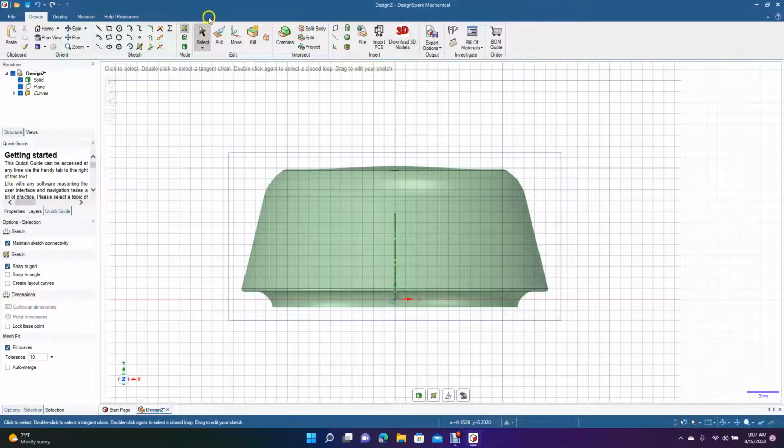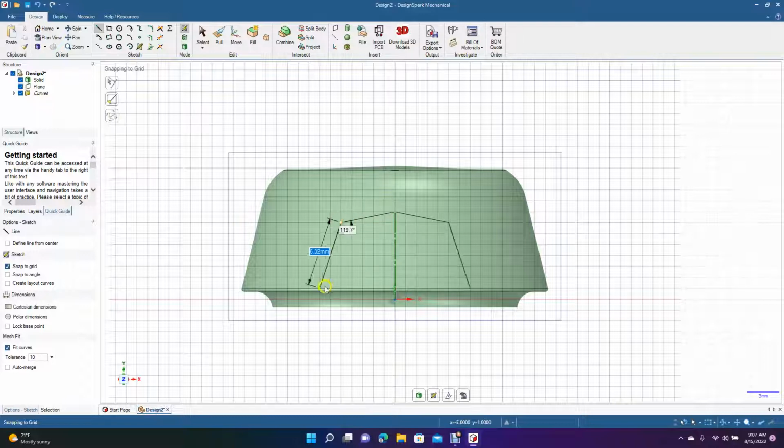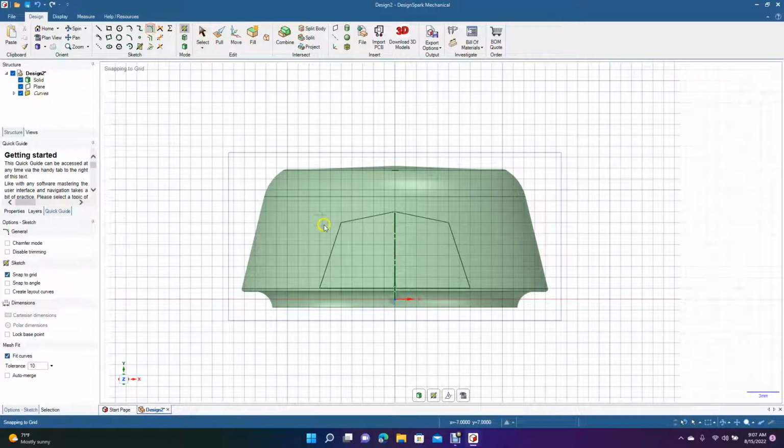And I'm just taking a kind of a reference from one that I have here. So we're going to go ahead and drag this piece out to about there, and then we're going to drag down, and this is where our buttons are going to go. And then we're going to drag over, make sure that that's a closed shape. Now we're going to come and get our create rounded corners. We're going to create a fillet there.